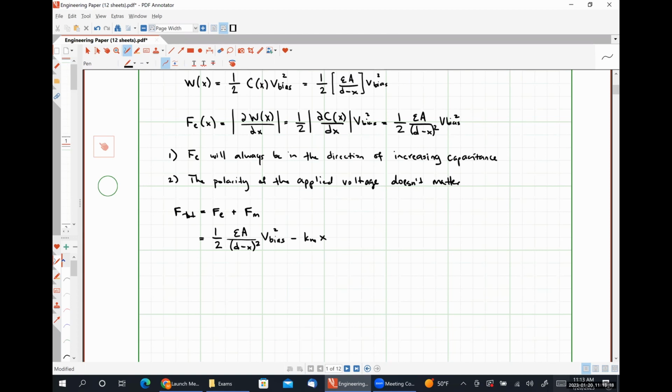And effectively, the pull-in effect allows us to actuate those switches, so close the contacts, by applying a pretty reasonable bias voltage to cause it to occur, because we're effectively exploiting the system's instability in order to do so. And then we actually in turn get to use an even smaller hold down voltage to keep the switch actuated.